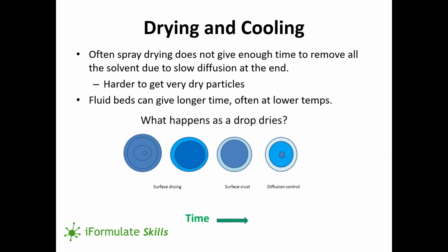Moving on, here's a description that you've seen before from Jim. It just gives you an idea as to why fluidized beds are often used as additional dryers. You can see that often it's difficult to get the very last part of a solvent out of the core of a particle by the time it's reached the bottom of the spray dryer. This is not a problem in lots of instances with spray drying, but it can be in certain circumstances, particularly when you realize that after the particle comes out of the dryer and starts to age, that liquid in the center starts to redisperse, and under some conditions that liquid can diffuse out to the surface and make the surface quite sticky, which is not to be desired.